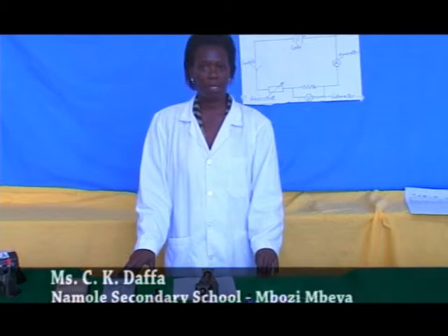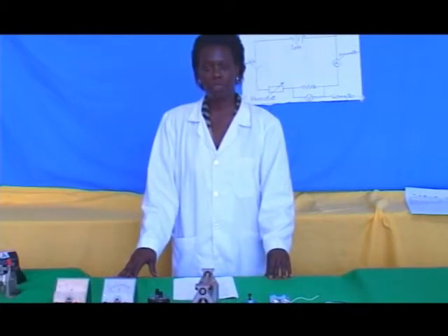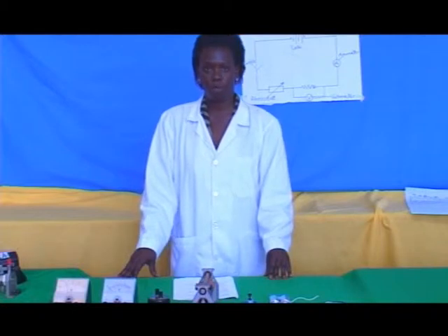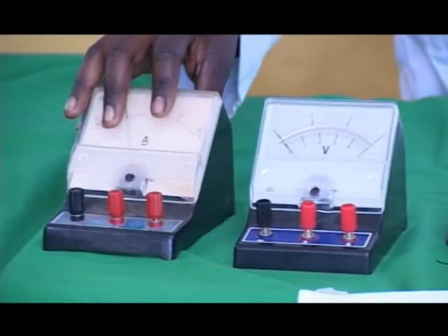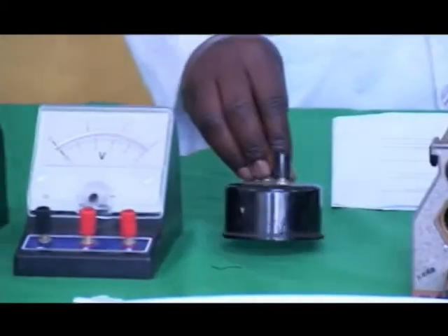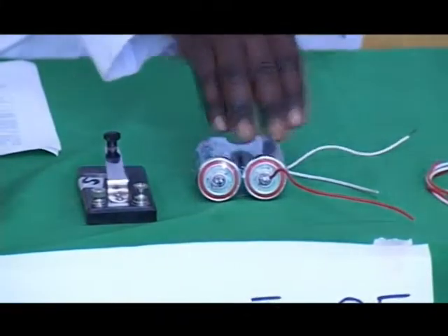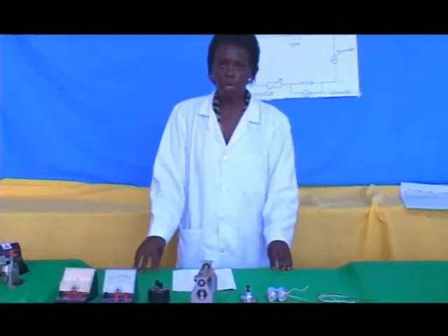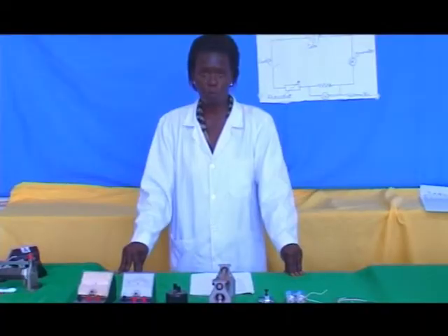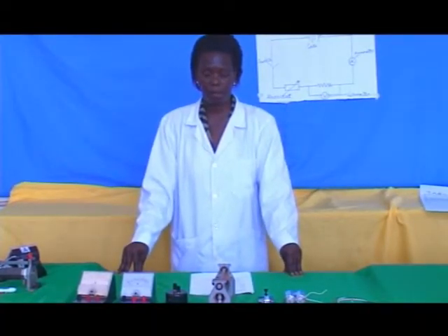An electric circuit is a continuous path taken by electrons to flow when electrical devices are connected. The aim of this experiment is to verify Ohm's law. Requirements: an ammeter, voltmeter, resistor, rheostat, a key, 2 cells, and connecting wires. Precaution: ensure the temperature of the wire is kept constant throughout the experiment by opening the key in each reading. Use small current.